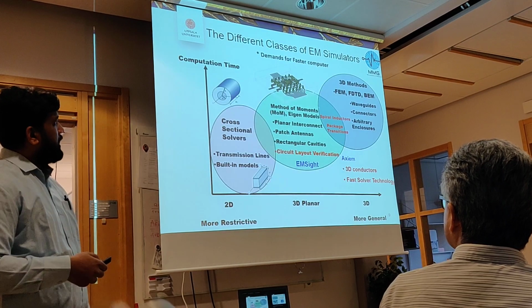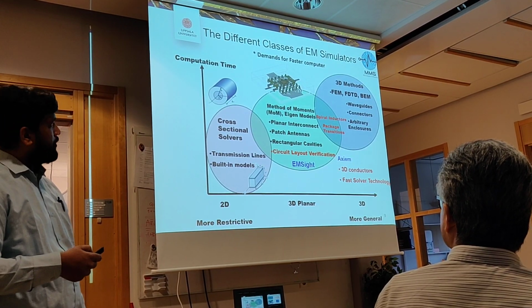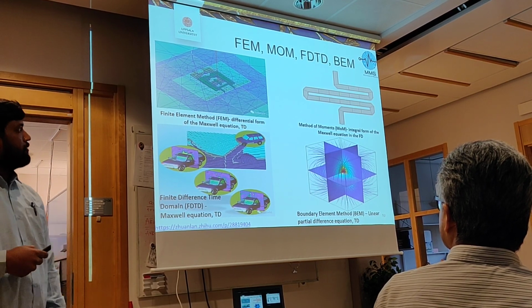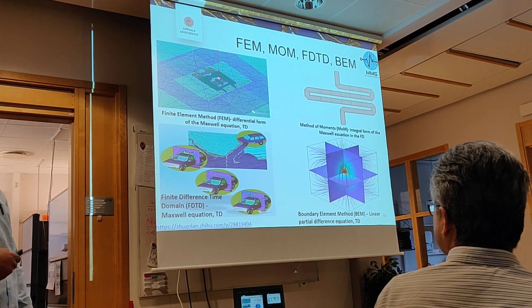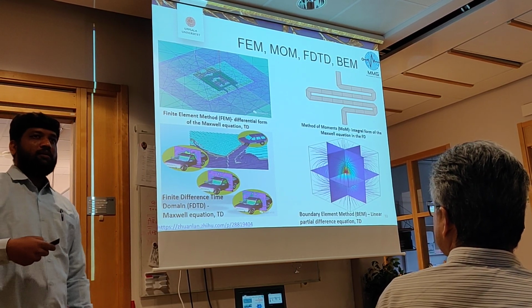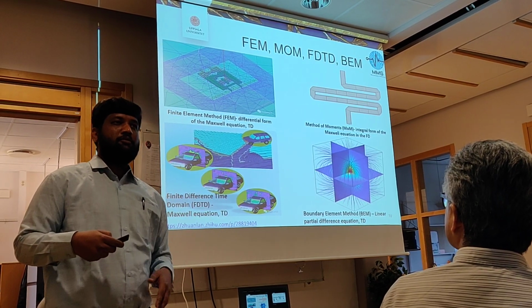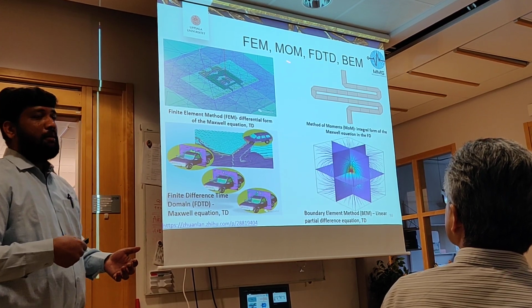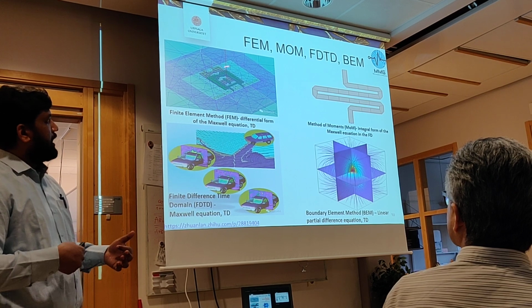And this part I will be again going into in quite more explanation. I want to distinguish between these for a designer. You have to consider these 4 techniques. Whenever you are using the finite element method, it will take any microstrip geometry or any kind of structure, divide it into multiple tetrahedrons and analyze it. It will apply Maxwell's differential form equations in the time domain and analyze.